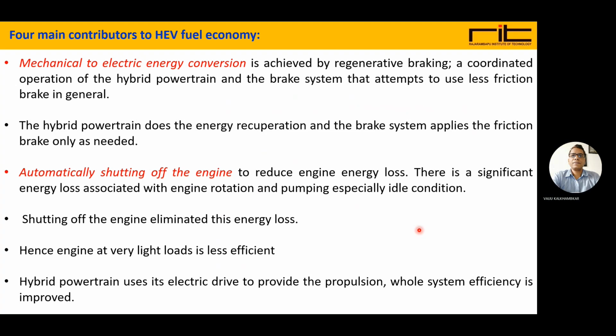Whenever the braking system is applied, instead of going for the mechanical brakes that waste the energy in friction, regenerative braking is the electrical braking where it will generate the electricity as well as apply the electrical braking. So this is one of the contributions of hybrid electric vehicles to the fuel economy.